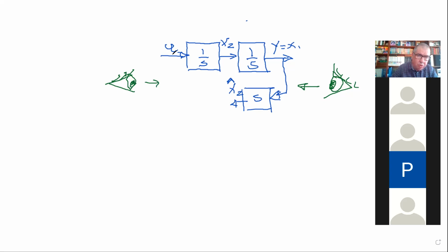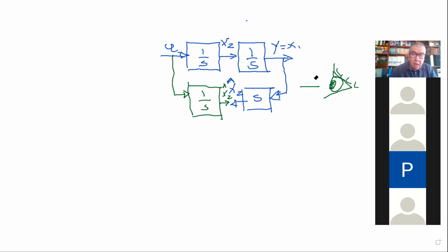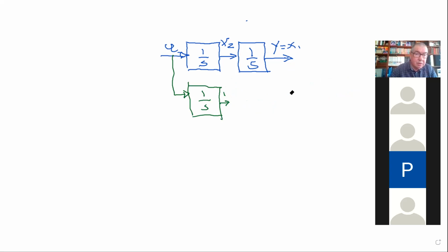So you pick up the u, and what do you use to estimate x2? I also use the integrator. Use an integrator. So if you have an integrator, then again, you have x2 hat equal to 1 divided by s. Okay? And the integrator is much less sensitive to noise, so it's much better. So we clear our eyes, and we have this.